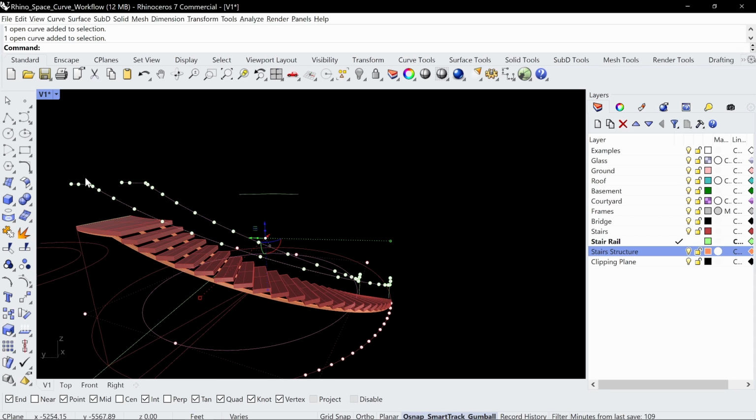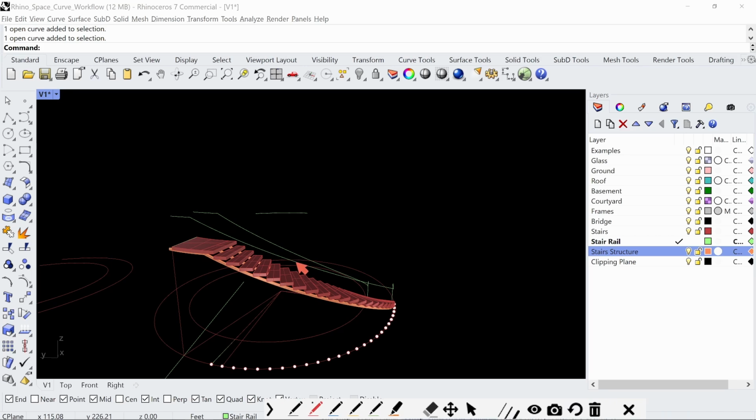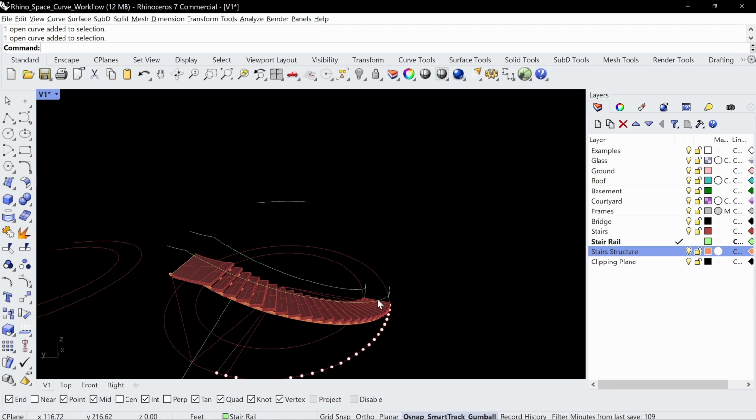Okay, so what we want to do now is give this little tiny balustrades of the column, or little tiny guards over here. Technically, if you have the rails, the spacing here can't be more than 4 inches apart. And you can calculate that if I just type in length, right? That's 41.63 feet. So if I do 41.63 times 12, that's 499, basically 500 inches. If I divide that by 4, I need to divide this by like 124 times to get a 4-inch division. So we'll do 124 just so you see what I'm talking about.